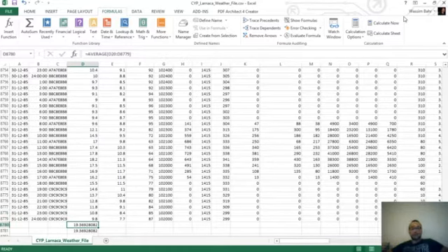We discussed in class the use of earth cooling, earth sheltering. These are strategies that use the stable ground temperature all year round, which is equal to the average yearly temperature of the location. So in Cyprus, Larnaca for sure, the average yearly temperature is 19 degrees, which is close to the comfort temperature 21.